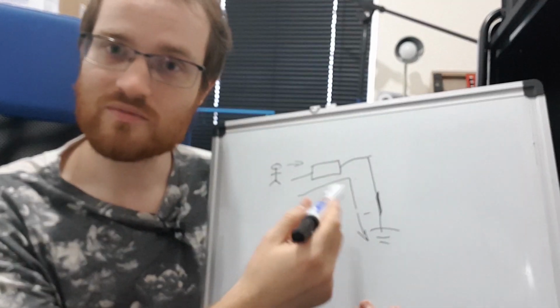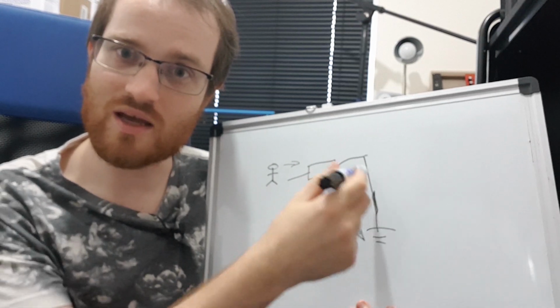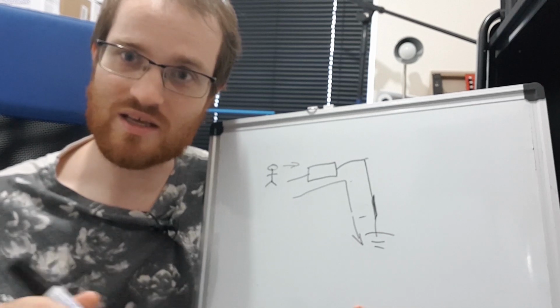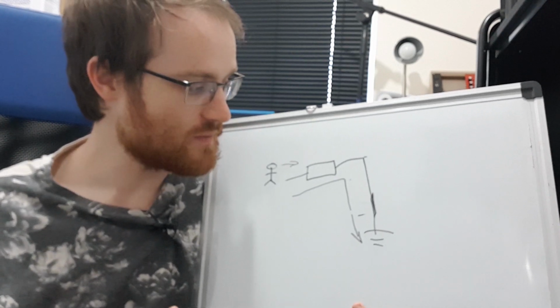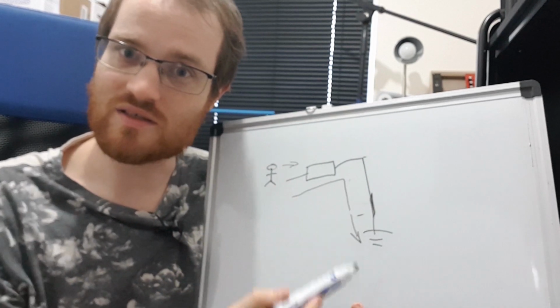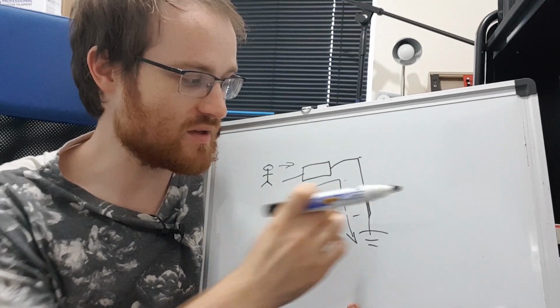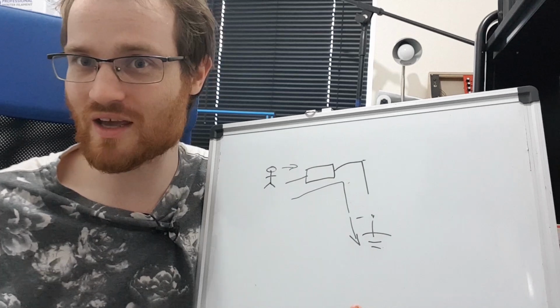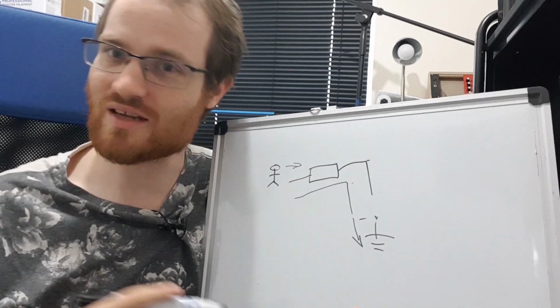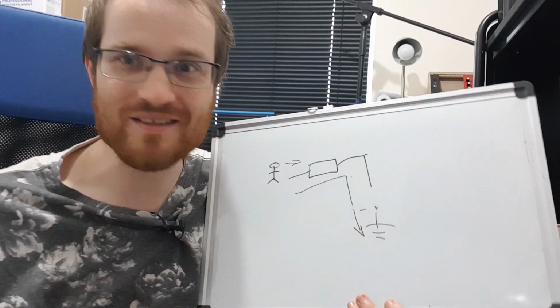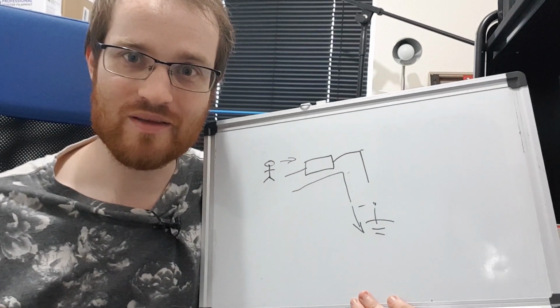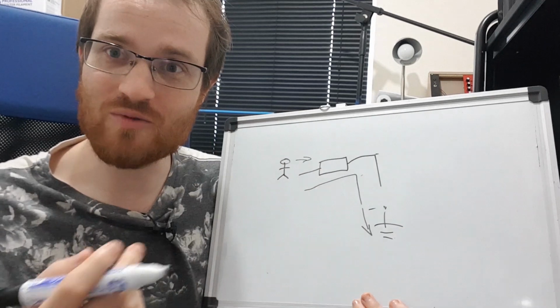But this value will change with frequency, and when it acts as a short circuit at high frequencies, essentially when your XC gets very small, the series combination of these two is at its lowest, because no matter what impedance this is, don't even worry about calculating it, doing all the complicated maths to calculate the impedance and adding them together. You just know any impedance is more than no impedance, so the series addition of these two impedances is going to be lowest when there's only one.